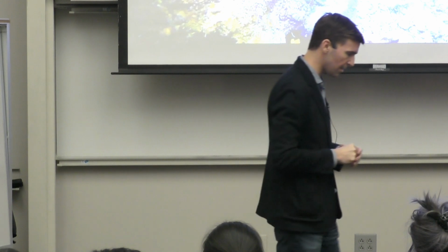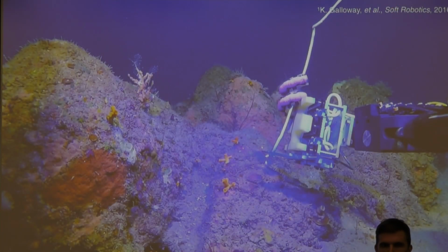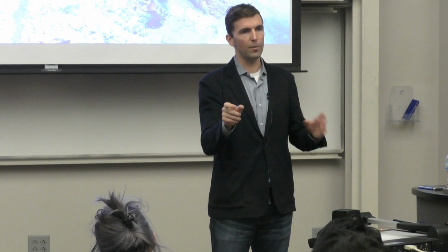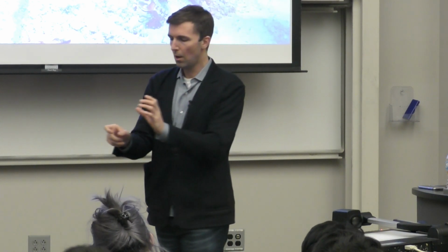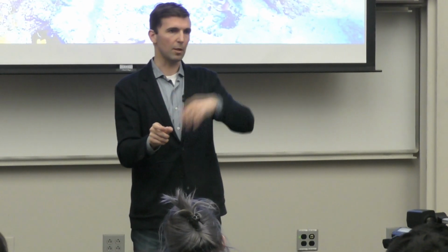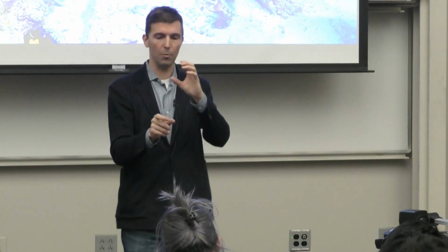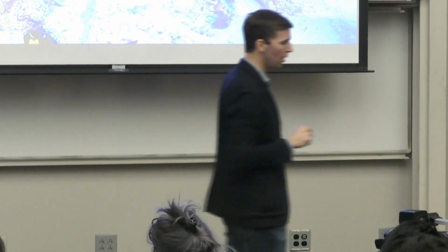You can contrast this then to the previous gripper that I showed, which is this metal gripper. Now, imagine if I want to do a pinch grasp on something like this, and I've got no feedback other than visual, very nice visual feedback. They have great cameras on these ROVs. But that's it, and it's only a 2D camera image, and I'm perhaps a kilometer or two above this on a boat that's rocking, and I'm teleoperating this. Doing a successful delicate pinch grasp using that technique would be basically impossible. So we're excited about this.